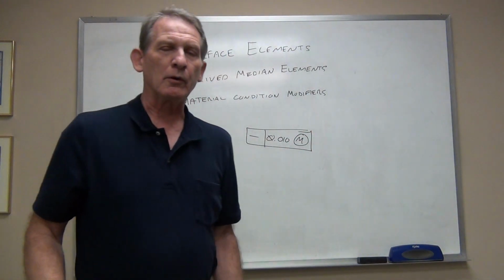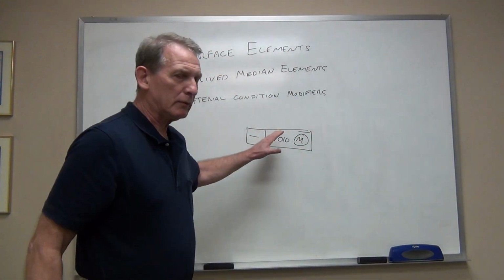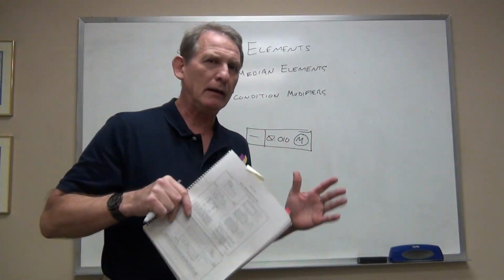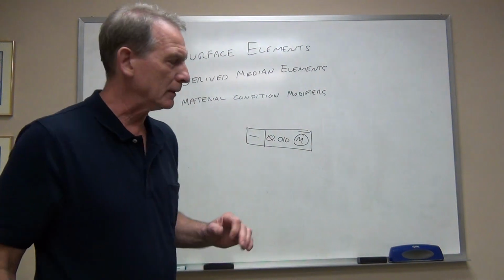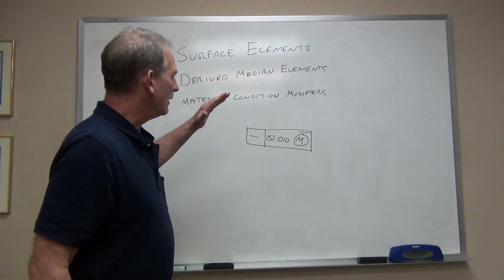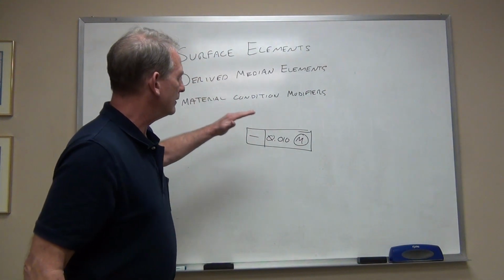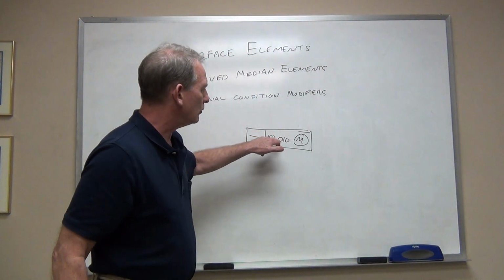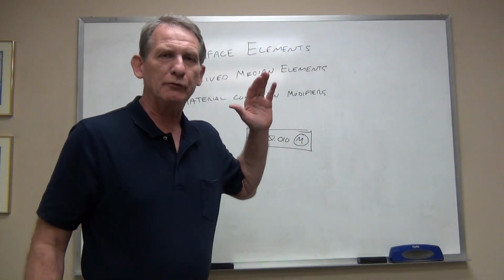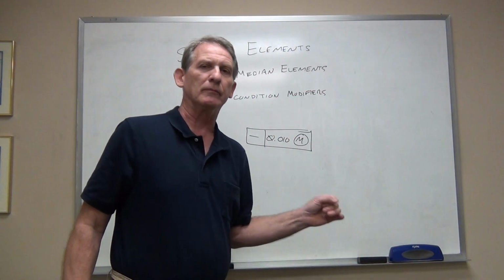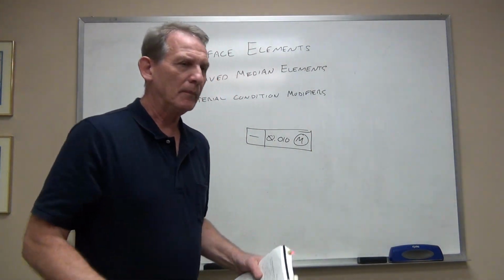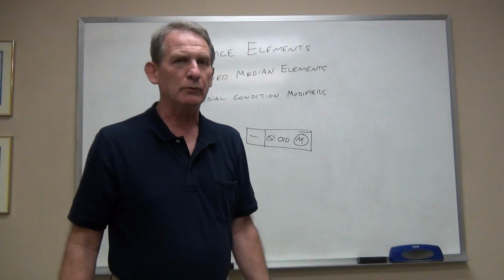And if you remember, we said that we want to be able to look at this very compact symbolic statement of requirement and be able to turn it into English. The way I would do that is to say, I have a straightness control with a 10 thousandths diametral tolerance zone, but that tolerance zone is 10 thousandths only when the feature is at maximum material condition. In other words, when the shaft is at its largest, I get a 10 thousandths tolerance zone.